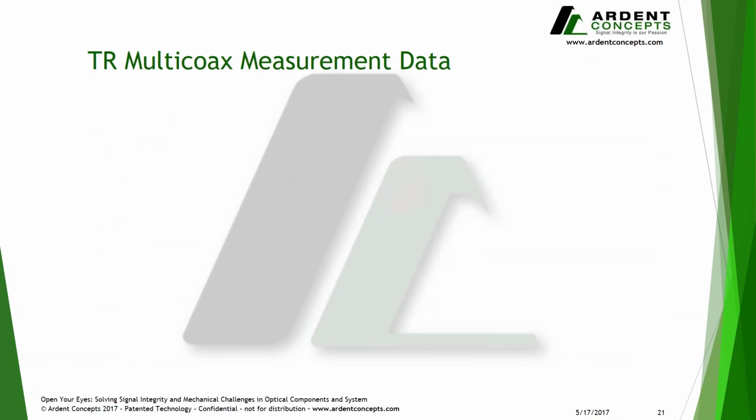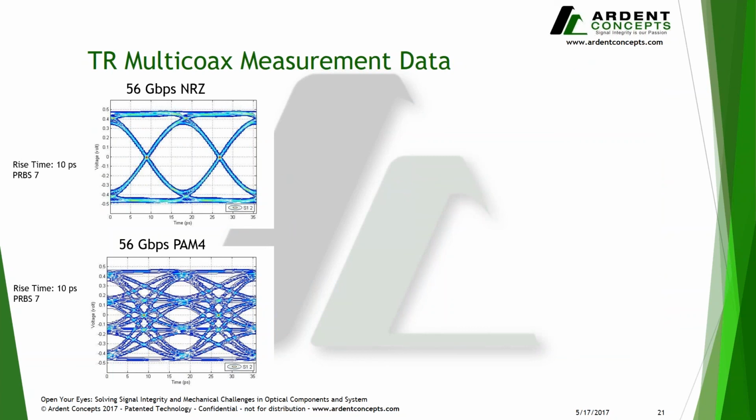So what does that measurement data look like if I was to use a TR device? Well, here we're running some pretty high data rates through that TR device. This is for a single lane, and we're looking at 56 gigabits, both NRZ and PAM4. Now, the TR device is being used in applications into some of the QAM, as high as QAM 64 scenario modulations. But as this is a typical application we thought we'd show, again, we have very clean and clearly opened eyes, good eye width and height, no intersymbol interference, which means no jitter.